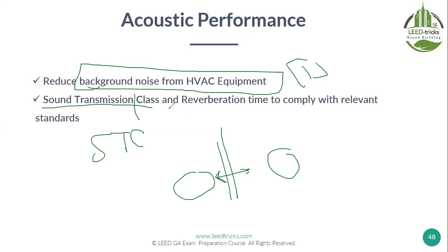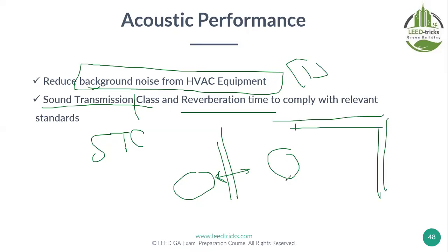The last thing is when you hear your voice repeated many times, we call it reverberation. You see in cinemas, they put some insulation in the walls to make the voice more clear. There is no repetition, so people will not feel a headache after a while and leave the movie. So for reverberation time, you need to put acoustic insulation in the walls, ceilings and also the floors. We notice in the cinema they put carpet floor or any type of soft floor that absorbs, not reflects.